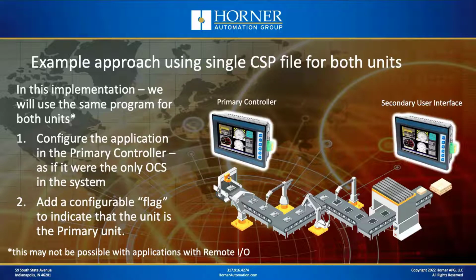Now, I will talk about a caveat here. If you are using remote I/O in the application, this approach I'm getting ready to show you probably won't work. That's because you can't have both units configured for the same I/O, remote I/O at least, fighting over who's in control. So for applications where there is remote I/O, this approach won't work. But in a lot of applications, there is no remote I/O. All the I/O is local, and so then it won't be a problem.